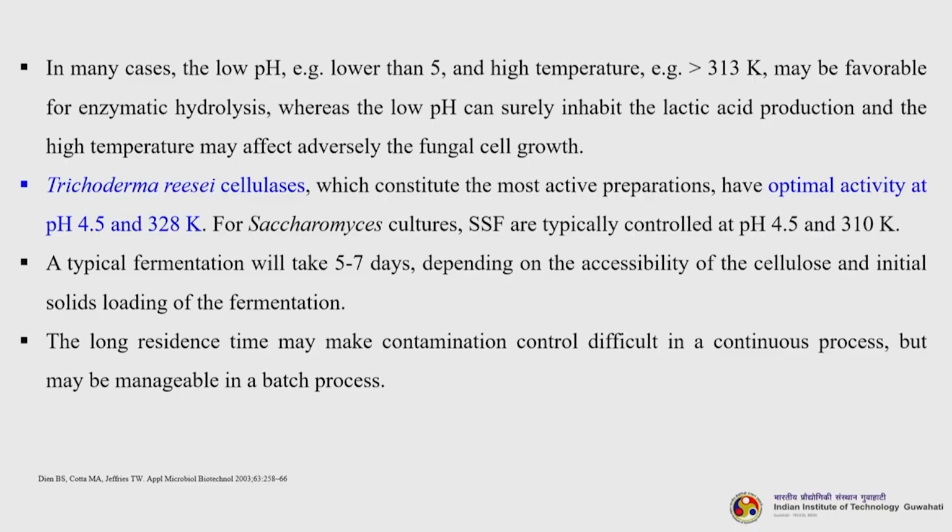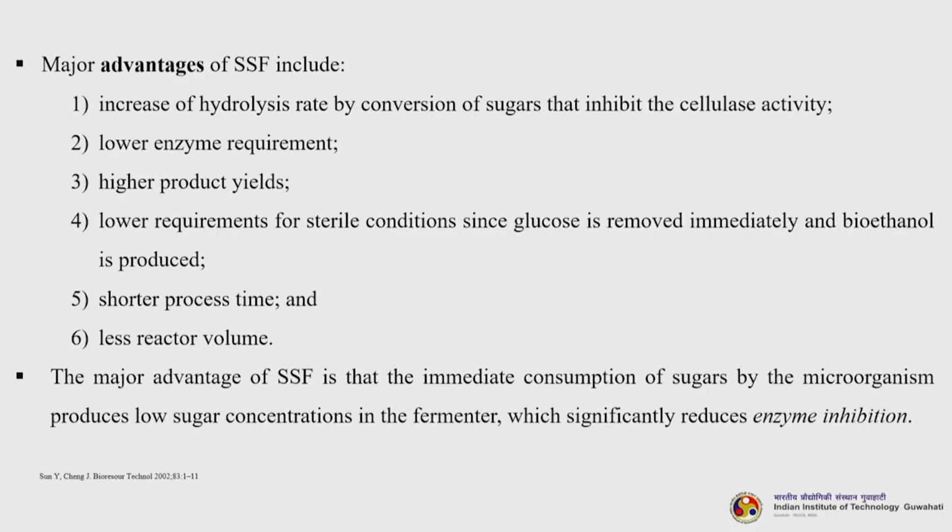A typical fermentation will usually take 5 to 7 days, depending on the accessibility of the cellulose and the initial solids loading of the fermentation. The long residence time makes contamination control difficult in a continuous process, but may be manageable when you go for a batch process. So, let us look at the advantages of this SSF.